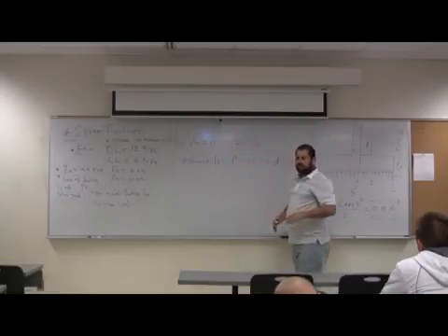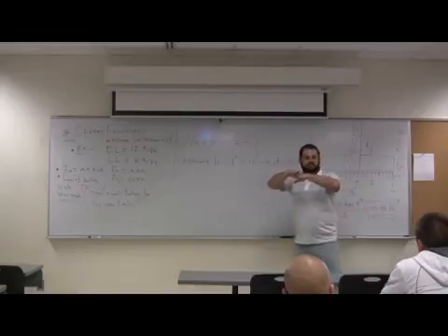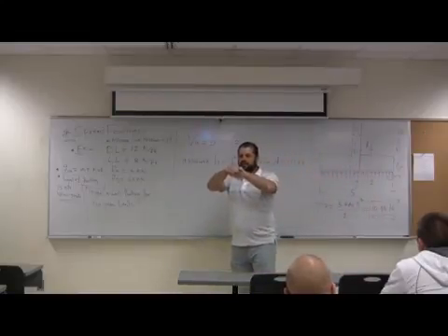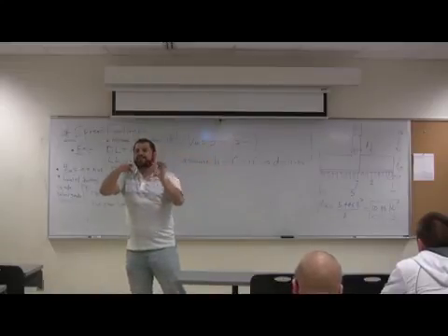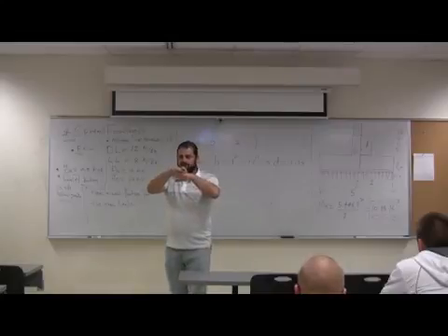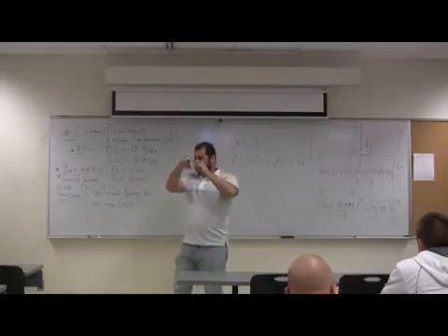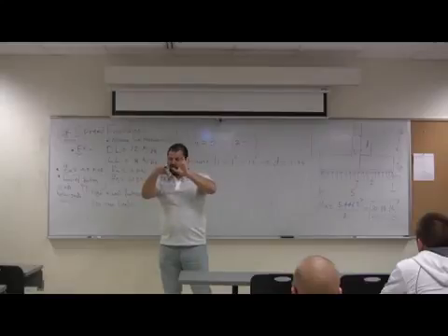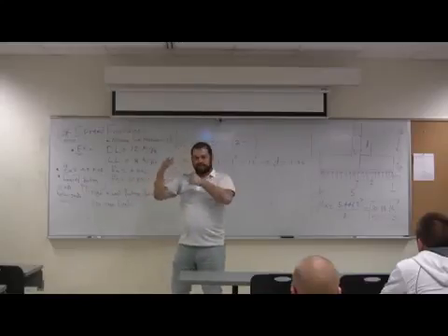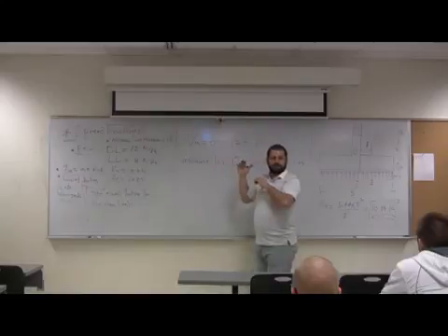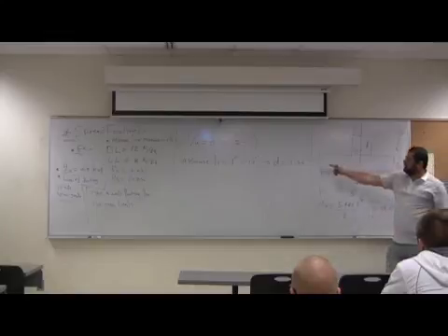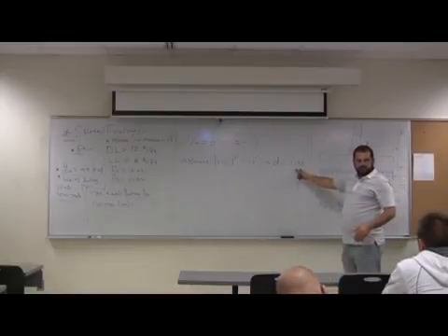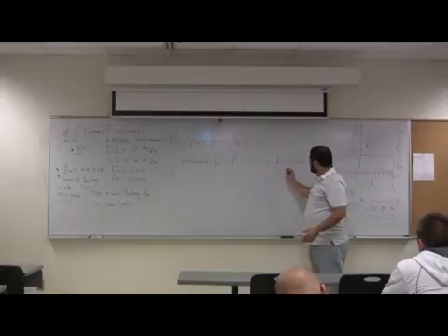Again, I said 4 or 4.5, I'll tell you why. Because in the single column footing, we will have 2 layers in each direction. We calculate D for the most critical one. So you're going to go to the second layer, the top layer. So you're going to have 3 plus the diameter of the bottom layer plus half the diameter of the top layer. That's why I said 4 to 4.5 there. For now, you just have 1 bar. To the center of that, we're going to take 3.5. Okay? So our D is 8.5 or 8 inch.